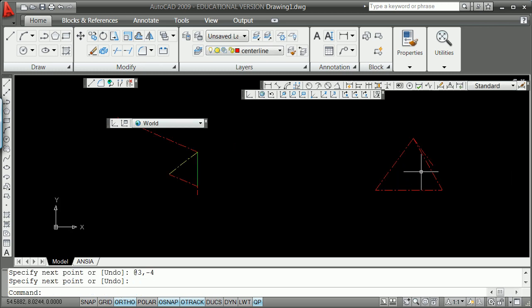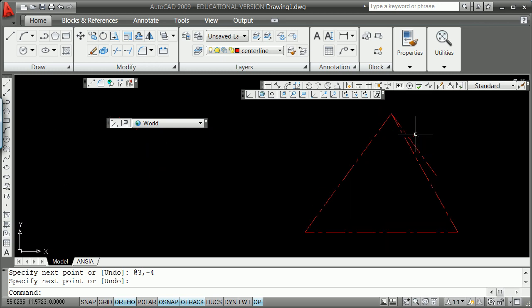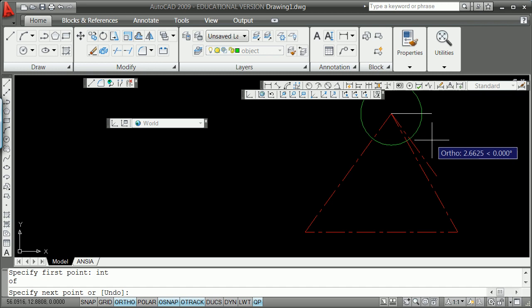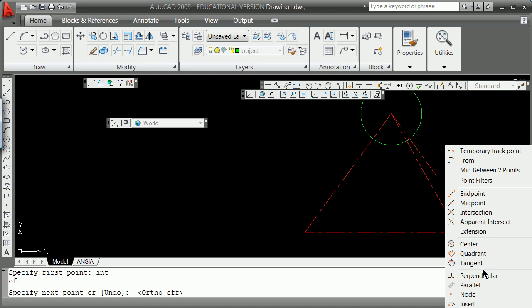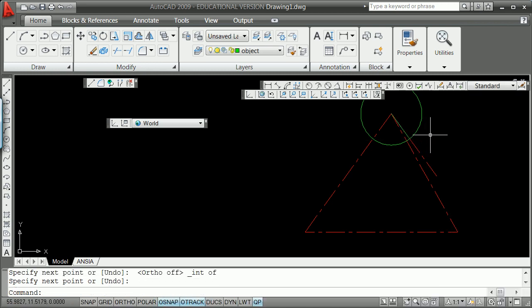Once again, the force vector here was given as 2, so you're going to, I guess, use 2 to be 2. That works for me. And you want to show the star diagram, so line from the endpoint there. Go ahead and change it to object, and you would have it on a force layer. Line from the, I'll do it again, circle from the end of here, radius of 2, line from the intersection. It's nice to draw your lines, and it's almost necessary to draw them in the right direction here. So that's one of the reasons you're drawing lines on top of lines. Intersection to the intersection. You've learned to use layers long ago.